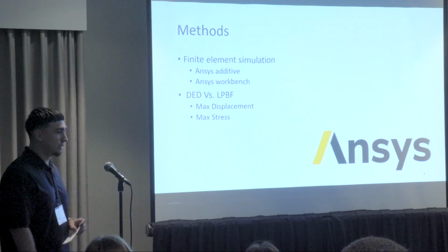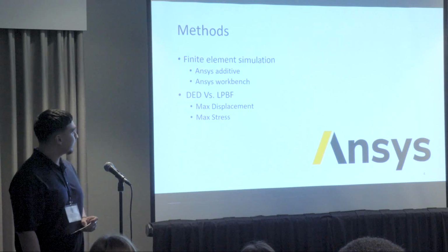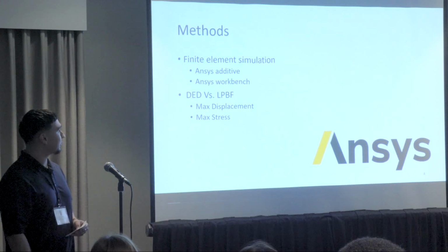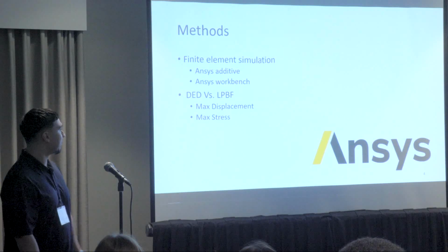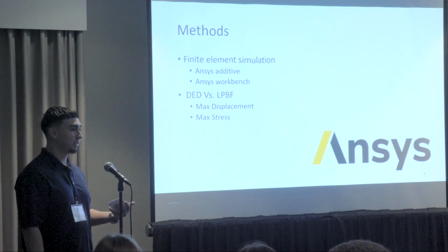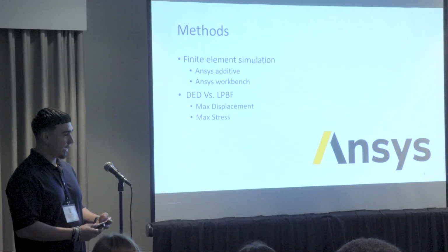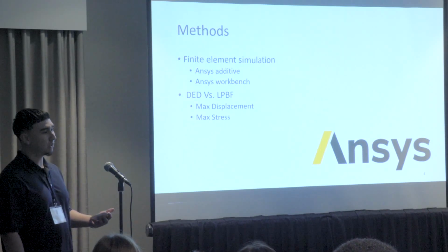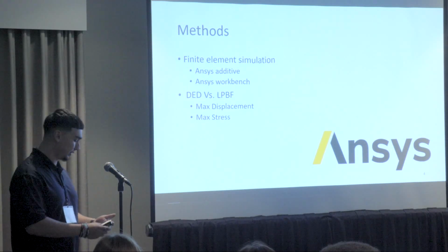For methods, we use finite element simulations. For laser powder bed fusion, we used ANSYS Additive. For directed energy deposition, we used ANSYS Workbench. We're taking measurements of the max displacement and max stress. We use the same material, which is titanium 6-4. We use similar but not the same parameters. The parts were created by a previous Spacecraft intern, Pablo, for his research project about laser powder bed fusion.